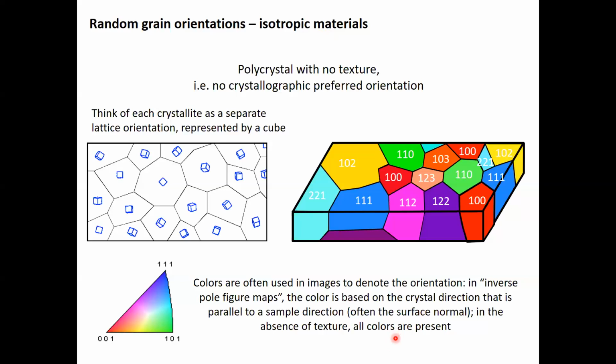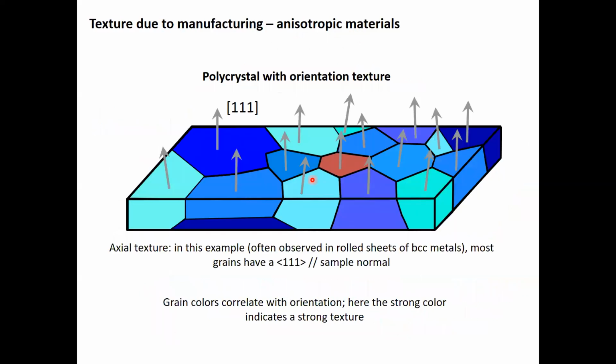So when the material is isotropic, in material science, we say it has no texture. Texture means basically when these polycrystalline grains are preferentially oriented in one direction. And this happens when you roll the material and you go through a manufacturing process where there's flow involved and you're making the crystal solidify and you're orienting the crystals in certain directions, right? So this is what a schematic for a texture would look like, right?